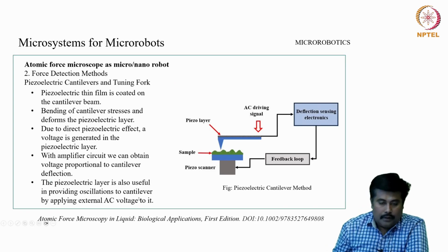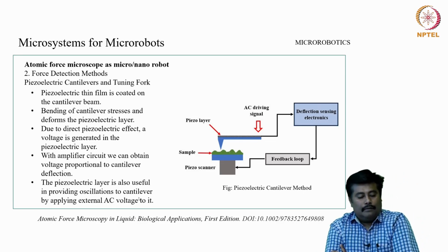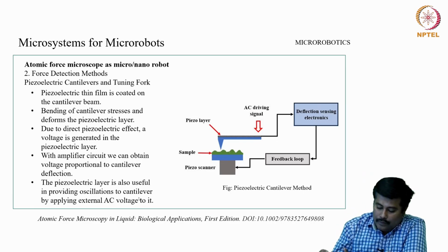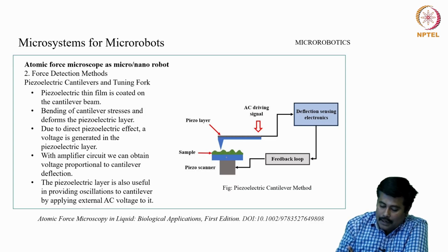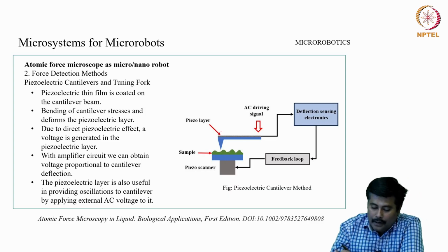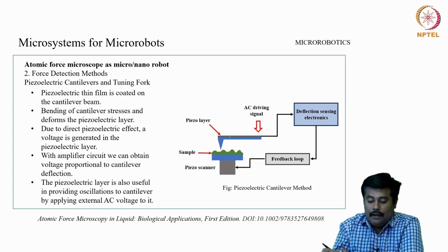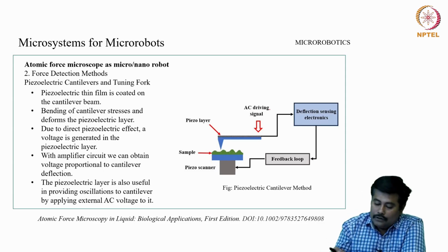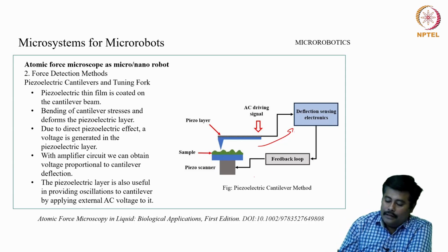Now, let us consider a piezoelectric cantilever and a tuning fork. In this particular case, we have a piezo scanner and then there is a sample. There is a piezoelectric layer over here which acts as a piezoelectric cantilever, and then there is an AC driving signal which is being fed over here. The deflection from the piezo layer is measured by the deflection sensing electronics, and then